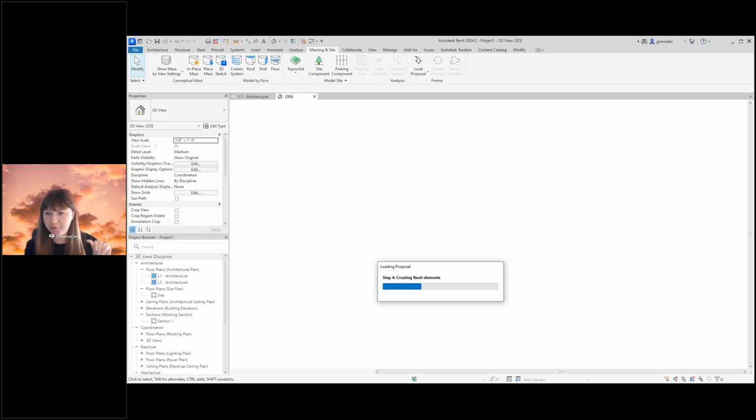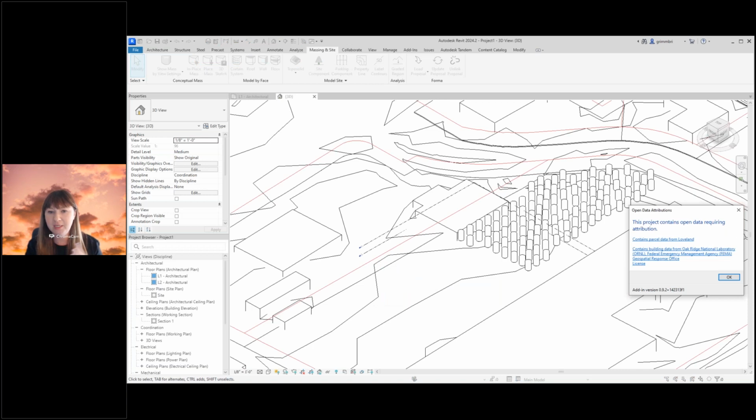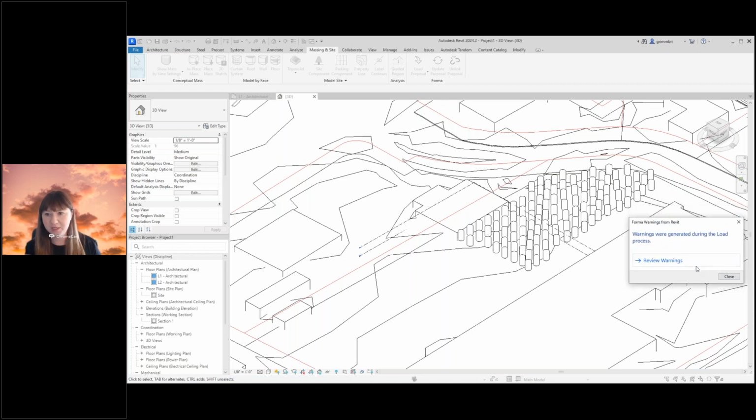And that also made me realize I forgot to mention one other thing too. We talked about the library at the very beginning when we were bringing in the context: the buildings, topography, property boundaries and roads. You also have the import option in there. So if you've got your own file from somewhere else, Forma will bring in object files and most 2D formats as well. You can use Forma as a conduit, really, to push and pull this data between a series of different places.